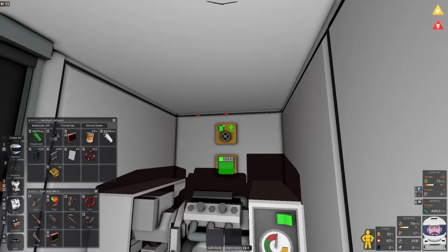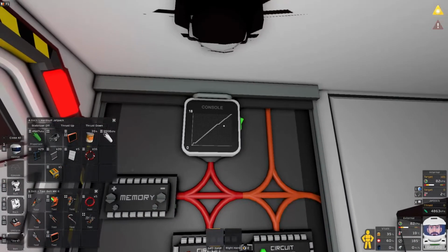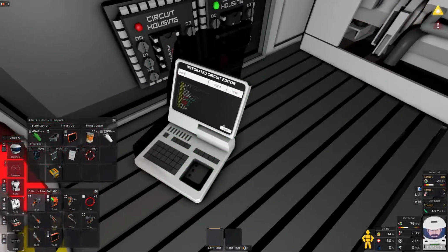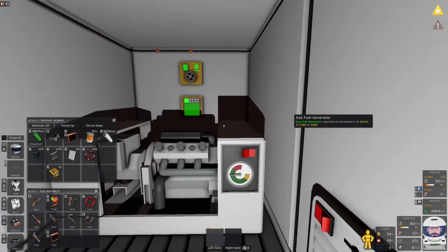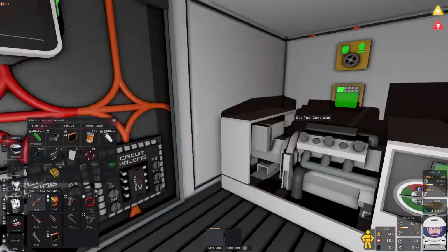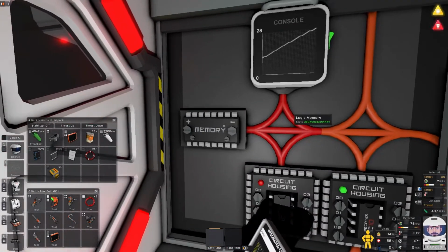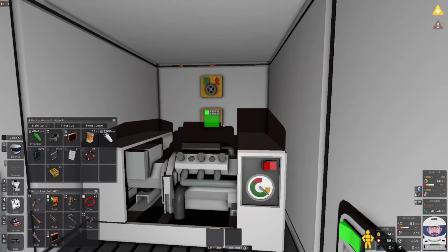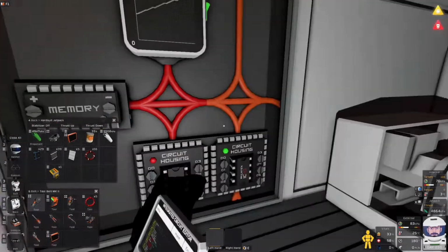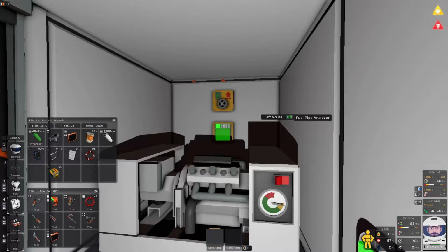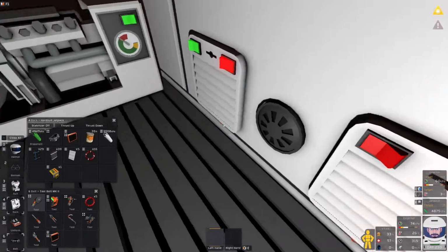Well, we're trying it with the pressure regulator, and it seems to be okay. I really don't think these other numbers are mattering at all, based on our setup. I've tried 2.5, 3, and 5, and set point is 20. Max output is 100, and it's not really doing much in terms of oscillation. It's just leaving a little bit of gas in the pipes, and that's getting used up. And once that gets used up, it goes back to doing nothing. So it doesn't really matter.